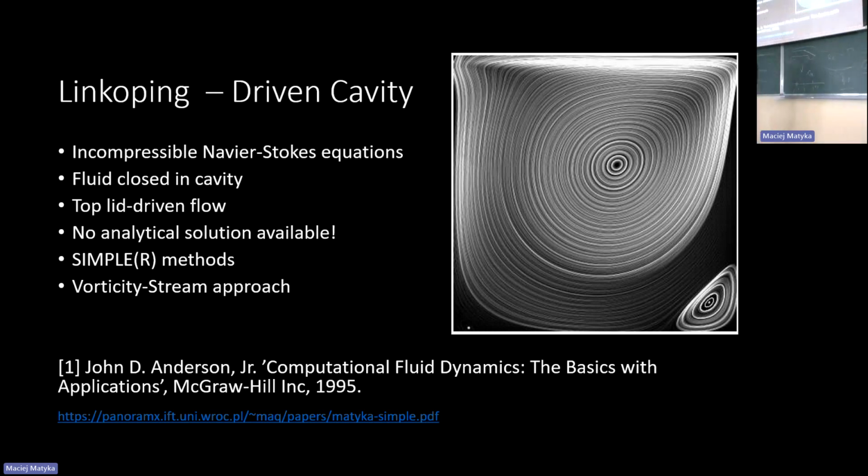It's the most standard, typical problem in CFD. It's a driven cavity. It's a physical phenomenon that happens in a system in which the fluid is closed in a tank. So we have no slip boundary conditions. You already know no slip was there. So you have no slip boundary conditions on all the walls except the moving top lid. And this lid is moving with some velocity, let's say u equal to u0.